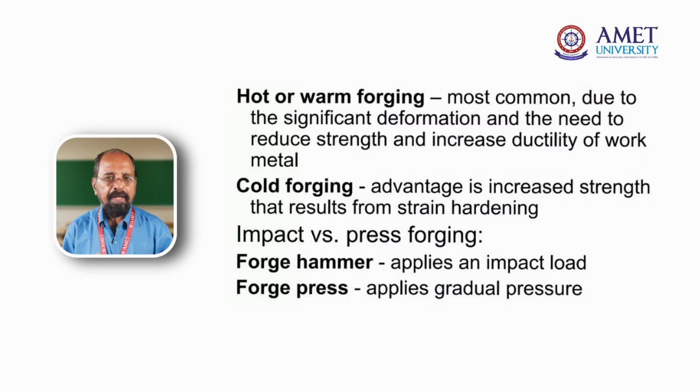The same thing can happen for cold forging also. The metal compression is done under cold conditions. In the hot forging process, the deformation is very fast, and more deformation is possible, whereas in cold forging, deformation is not as possible, and more force is required between the die and the punch. In the hot forging process, the mechanical strength is a little bit lower compared to the cold working process.